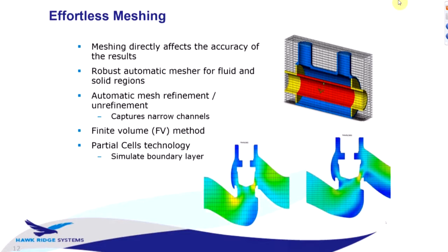Right, so with this here, a big concern with any FEA software or CFD software for that matter is the meshing, right? I know that with different softwares with CFD, the mesh parameter is a little bit cumbersome, right? It's not too intuitive. With Flow Simulation, the meshing is automatic, right? I've used Flow Simulation for a while now. I've taught it, and the meshing parameters are very easy to use, right? The automatic parameters that are set are pretty good from the get-go. And then, of course, there are also tools to refine it a little bit more in the areas of interest. But it's very effortless.